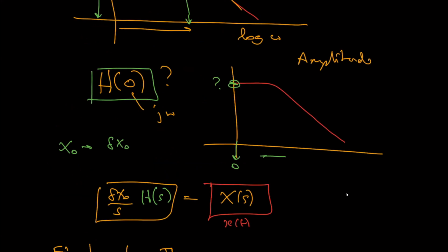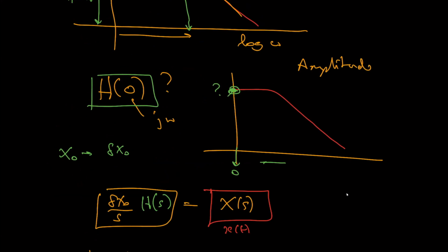All right. So this value here, this intersection here, is actually dXss by dX0. All right. And we'll come back to that in the future. So that gives us an interpretation for H0. It's just the sensitivity of the steady state level of the system with respect to the input. Okay. All right. And that completes it. We'll do an example of this in class then to show that this is indeed the case for simple systems. Okay. We're done. And I'm going to upload this.